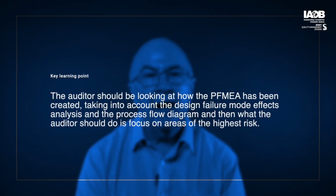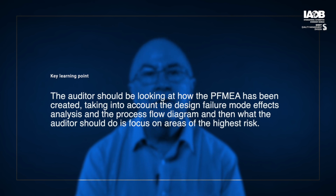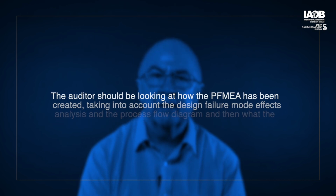You're welcome. So the key learning points. One of the key documents that auditors should focus on in auditing IATF 16949 is the process failure mode effect analysis, shortened to PFMEA. The auditor should be looking at how the PFMEA has been created, taking into account the design failure mode effect analysis and the process flow diagram. And then what the auditor should do is focus on areas of the highest risk.